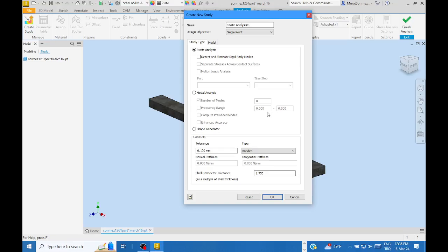If its balance is not so good, it has some undesirable runouts, and while the motor is rotating, it sets centrifugal dynamic loads onto the structure of the object. So if the frequency of the rotation, the period of centrifugal forces, becomes equal to the special frequency of the structure, instead of saying special frequency, commonly we say natural frequency, then resonance will occur.